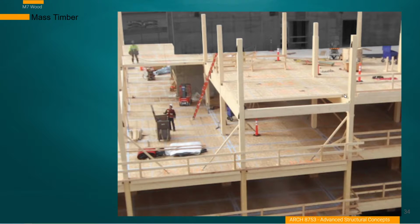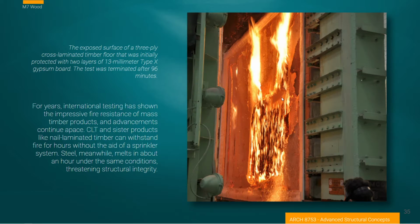You can see how they're halfway onto the span of the supporting beam. And you can see these little metal clips that are receivers for other clips that are probably embedded in the beams in this assembly. And a lot of that goes to helping make the frame a little bit more rigid. Also interesting to notice this idea of the continuous nature of the columns in order to create probably a little bit more lateral stability, especially during the erection of the building.